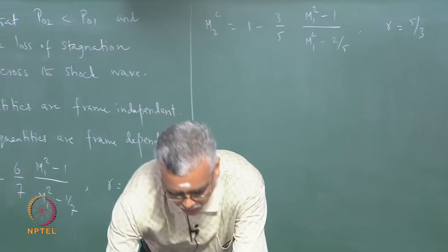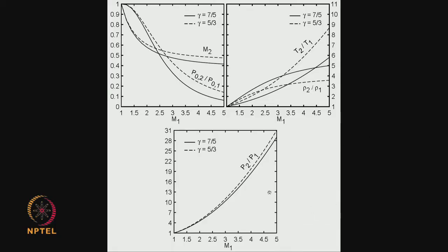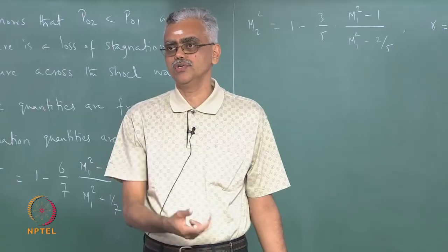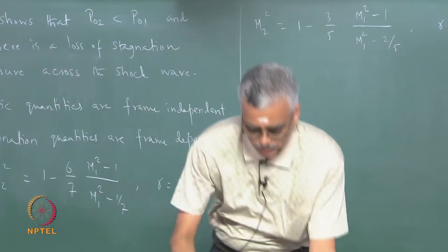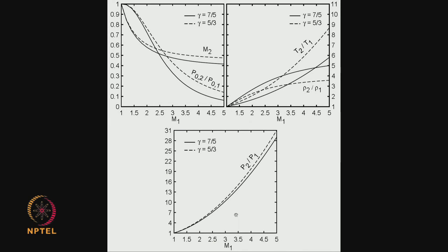So, this tells you how or why at higher flight Mach numbers I can do away with the compressor, and if I do this properly I can actually compress the flow to the required pressure ratio just by decelerating it. That is what this graph is telling you.